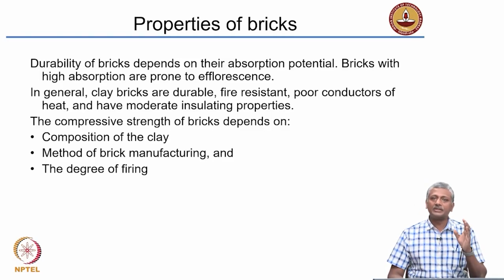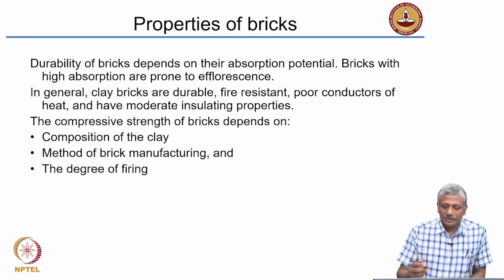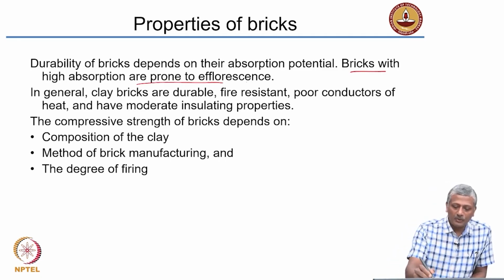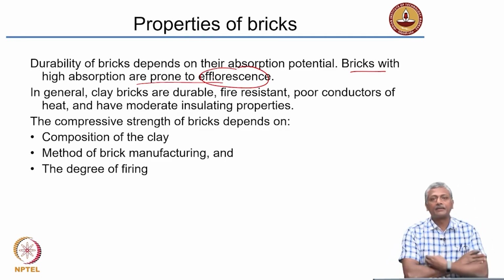Now, as I said, typical building bricks are designed for their strength and for their resistance to water absorption. Okay. A lot of the issues of durability of the bricks deal with the absorption of moisture by the brick. Okay. And that is a very important aspect to remember. If you can protect your brick from moisture absorption, you have greater durability that you can get from bricks. Okay. Bricks with high absorption are prone to what we call as efflorescence.